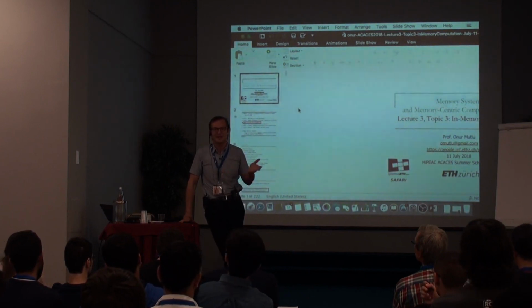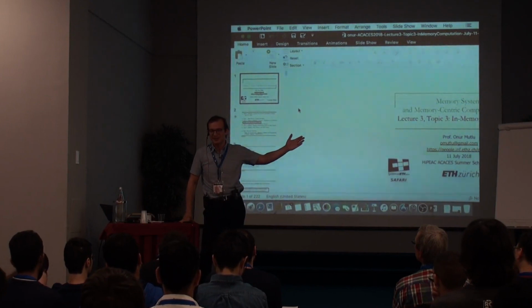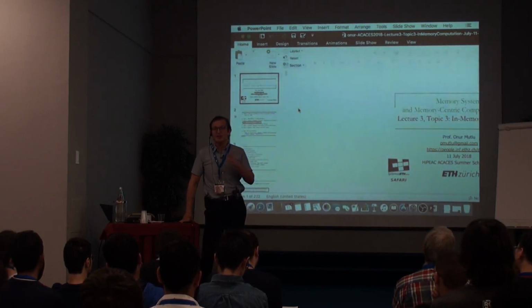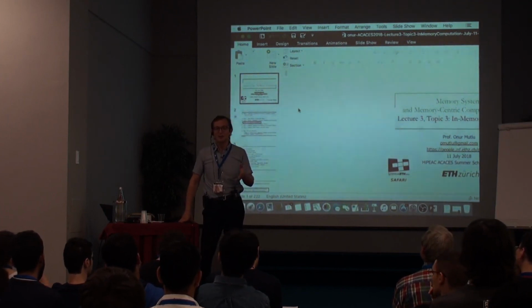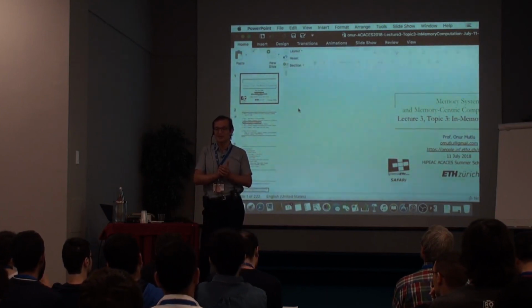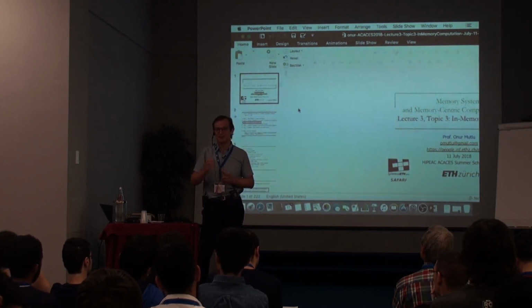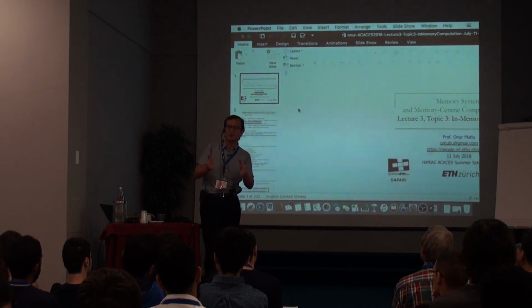But if you look at a data center system, there are a lot of cell errors, single-bit errors or multi-bit errors in the cells. There are a lot of channel errors also. And it depends on how good you are with the system design. As I said, if you haven't seated your DRAM really well, then your channel errors become dominant at a given point in time. And also, we don't know what we don't know, right?